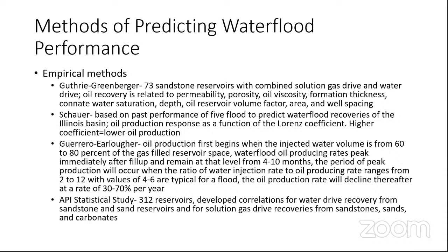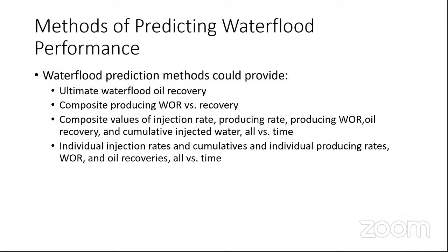And then you have the API statistical study of 312 reservoirs, which developed correlations for water drive recovery from sandstone and sand reservoirs, and for solution gas drive recoveries from sandstones, sands, and carbonates. So waterflood prediction methods could provide ultimate waterflood recovery, composite reducing water oil ratio versus recovery, composite values of injection rate, producing water oil ratio, oil recovery, and injected water, all versus time. Individual injection rates and cumulatives, and individual producing rates, water oil ratio, and oil recoveries, all versus time.